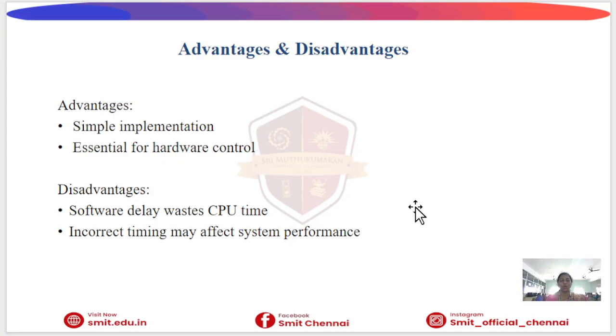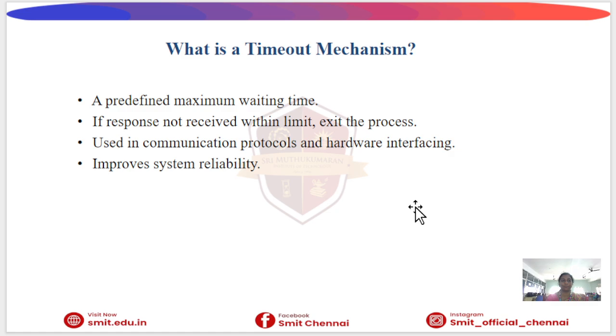The disadvantages: software delay wastes the CPU time, and incorrect timing may affect the system performance. The incorrect delay affects the system, so the efficiency will get low. If the delay is too small, the LCD may show garbage data. So these are the disadvantages of the hardware delay.